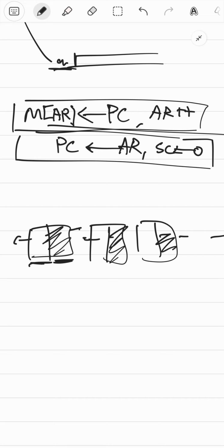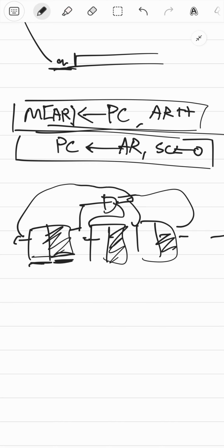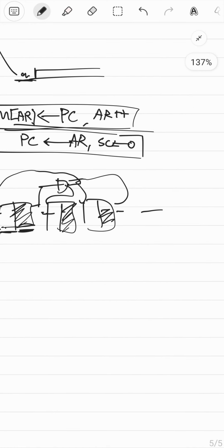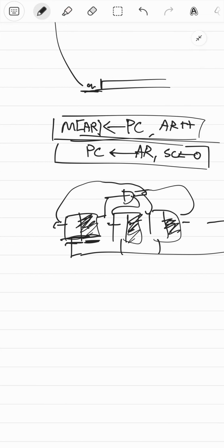So a counter basically has the input as some logic function of all of these, and it just sends the value into this thing, right? It's actually like toggle flip-flops, but that also is just D flip-flops in the end, so never mind all that. Just think of everything as D flip-flops in the end. The point is, all of this happens synchronously, so you have the same clock for every single thing. And so what happens is, you have these outputs of the logic. All of these are suddenly stored into this negative part of the flip-flop, for all flip-flops in the counter, but these are unchanged, right?